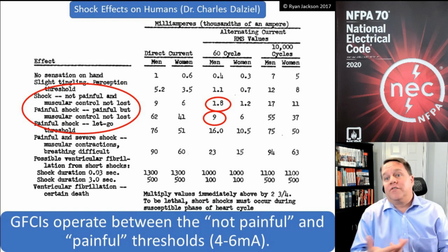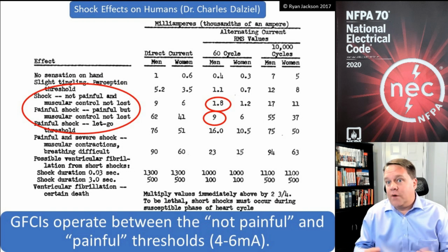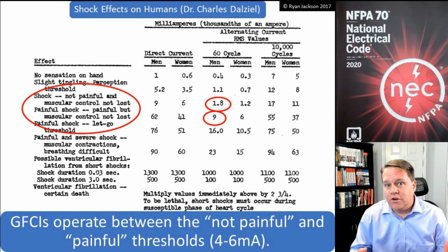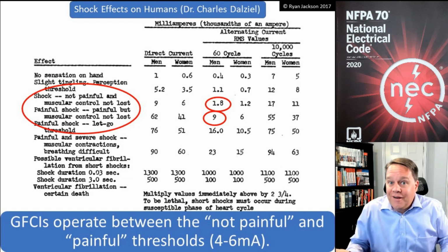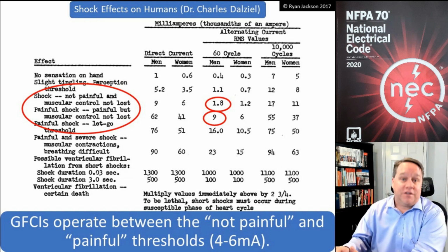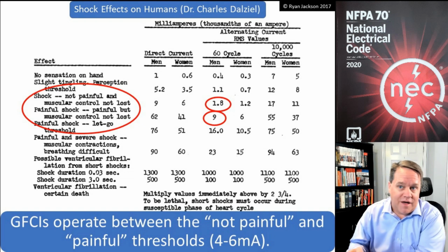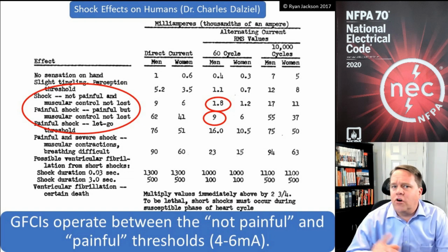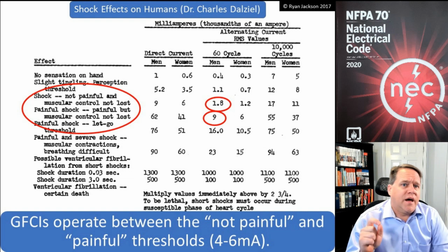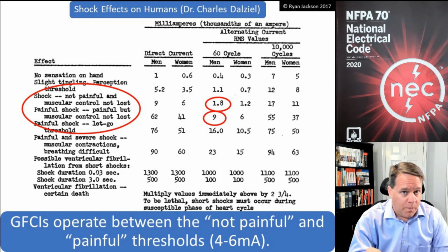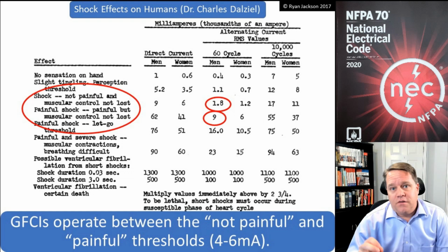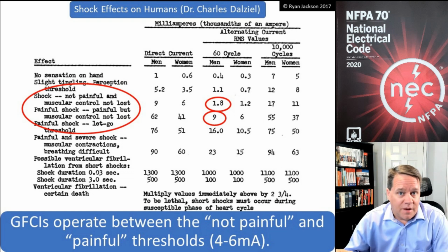So we came up with a concept like a GFCI, but it tripped at 1 amp of leakage current. Well, 1 amp, you're deader than dead if you have 1 amp flowing through you. So that doesn't protect anything. Dr. Charles Dalziel did research and actually figured out where the device should open. And then he patented his Class A and Class B GFCI protection devices.